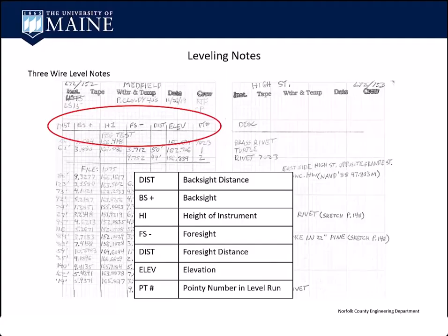So I'll talk about this more a little later, but you just have to know the metadata of your data. So this is NAVD 88, and the elevation posted was in meters, and I don't work in meters. I was in Massachusetts. It was a U.S. foot state, so I used the appropriate conversion to get into feet, and then we were off to the races.